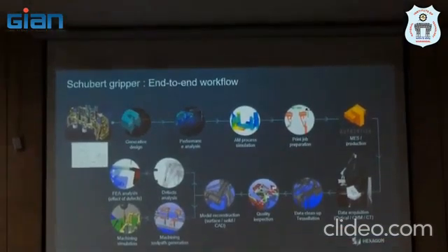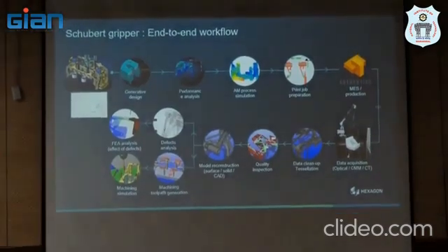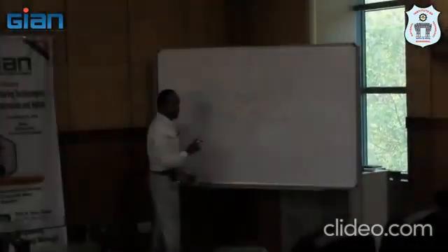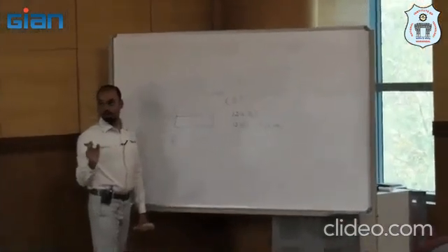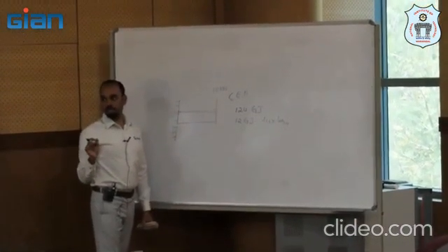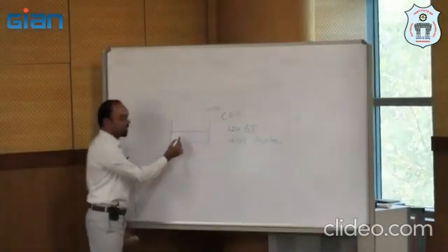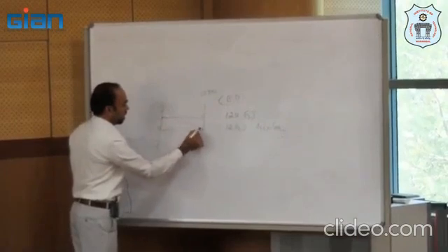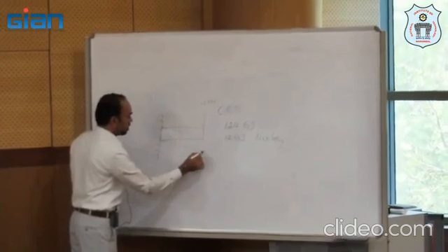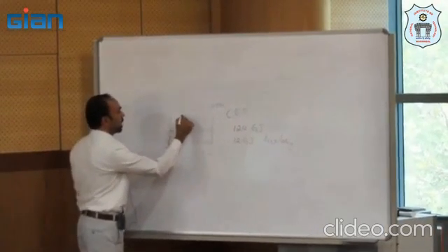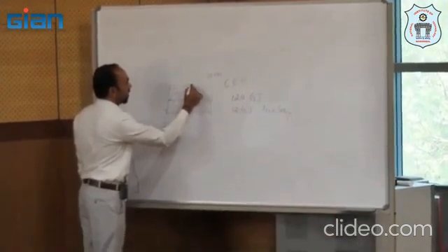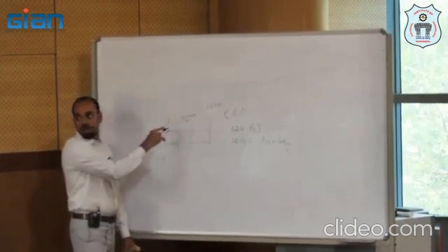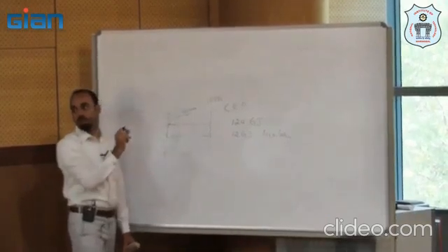Here I have a cantilever beam, and this is 10 kilonewton. Now I will not define the material. What I am interested in is, when I apply 10 kilonewton, what is the stress generated over here? Let's say it will bend like this, and there might be more stress generated over here, which is 320 MPa. So my target is to find a material which has a yield strength of 320 MPa.